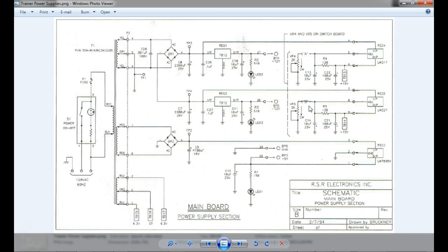So the odds are, the standard power supplies that we normally see, we see plus 12 all over the place. We see minus 12 all over the place. We see plus 5 all over the place. That's basically what we power up digital logic with, and then 24 volts. So odds are, with these standard DC power supplies that are out there, you're going to be able to find a fixed regulator that does that for you.